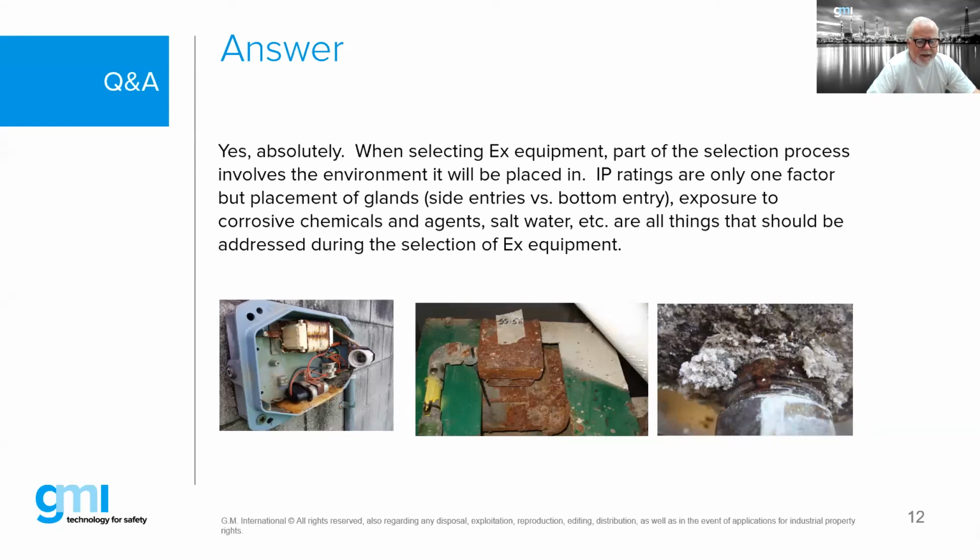But we will find that in certain environments, we might see things that, quite frankly, will be destroyed within a year. So we have to select the appropriate equipment, install it in the appropriate fashion, make sure it has good ingress protection codes, make sure the materials are appropriate for the environment. So yes, absolutely, we need to pay close attention to high humidity as well as saltwater environments or a particular corrosive agent.